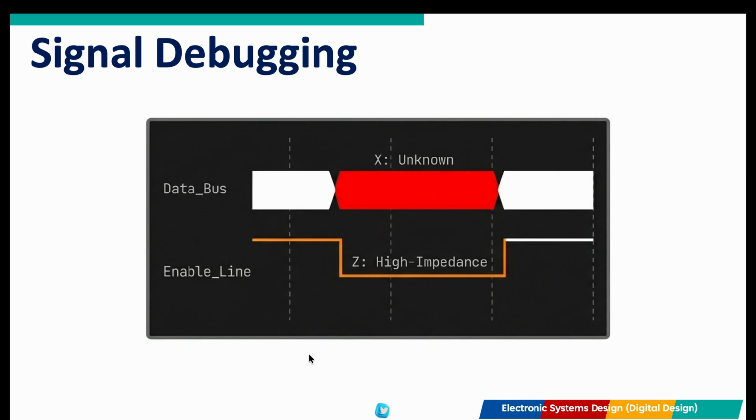Finally, you can use the $dumpfile command to export your simulation data into a VCD file, allowing for deep waveform analysis in advanced viewing tools. Master these steps and your hardware implementation will be right the first time.